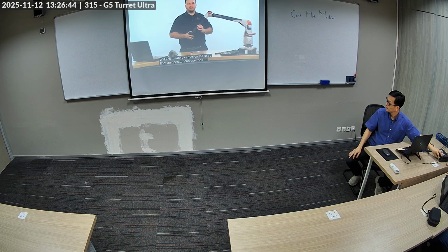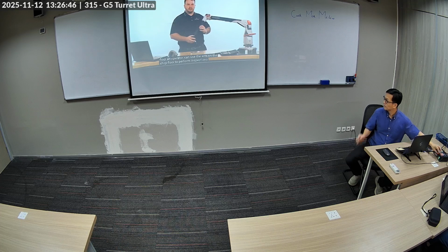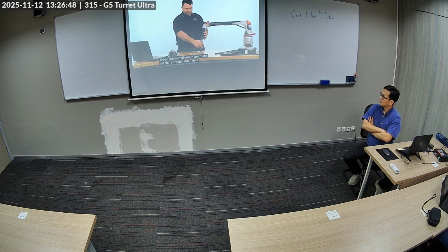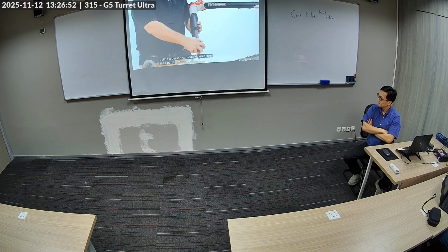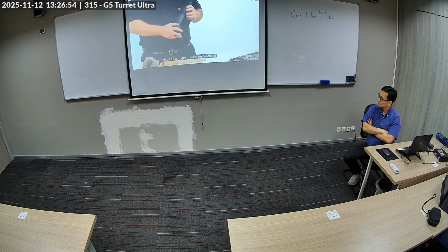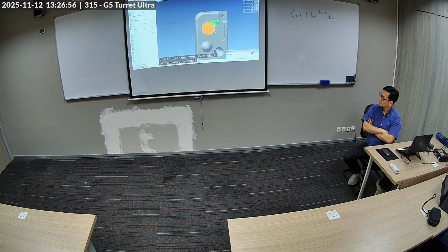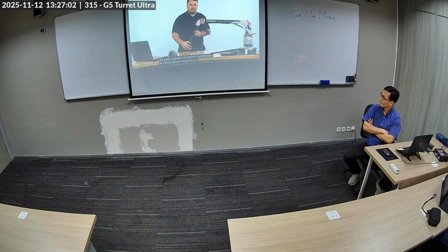An operator can use the arm on the shop floor to perform inspections, machine setups, and fixture builds. A person can quickly measure their parts and get immediate feedback of in and out of tolerance conditions. The Romer can also be utilized by your inspection team to perform full first article inspections using many different software packages.